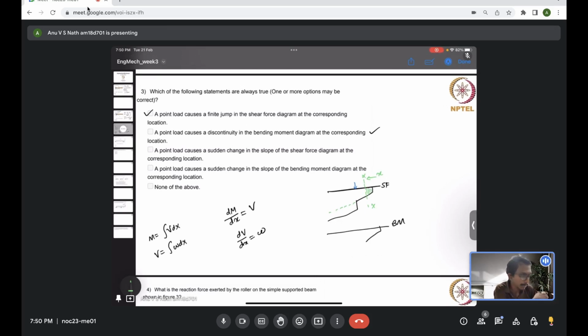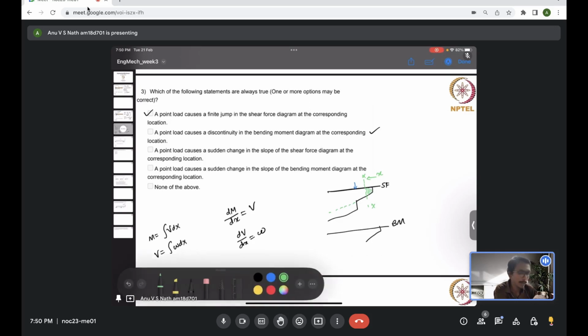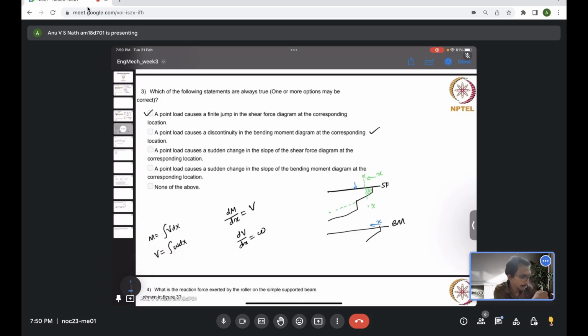I hope you already understood that concept from the lecture videos. So we will mark that as the bending moment at the location x, and we will plot that in the bending moment diagram following the x direction. So let's say this is the bending moment at the location x, the area under that particular marked region. That will be this value we are plotting here.